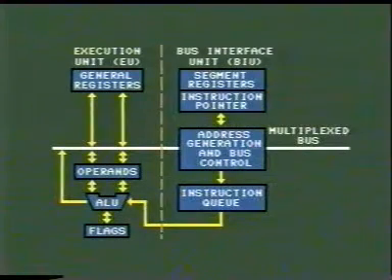8086 architecture. Pipelining has been incorporated in 8086 by providing two independent processors called execution unit, or EU, and bus interface unit, called BIU, allowing instruction fetch and execution operations in an overlapped manner.